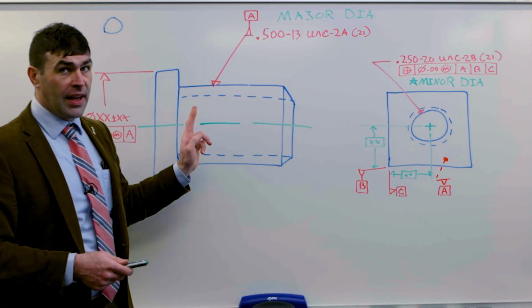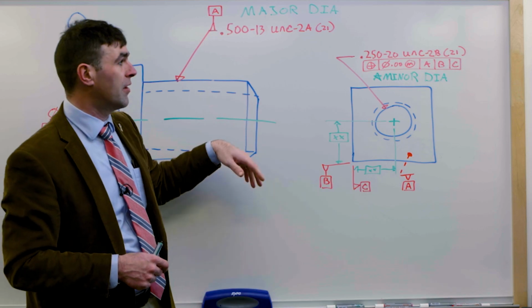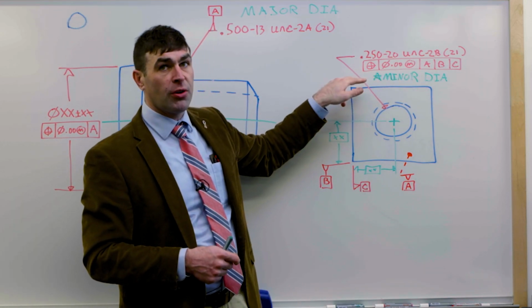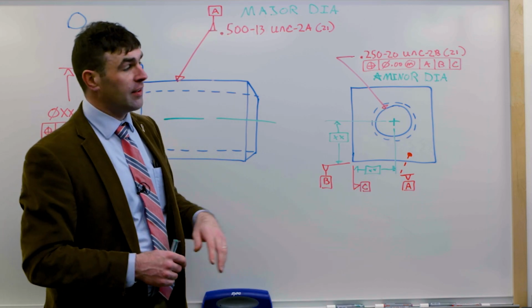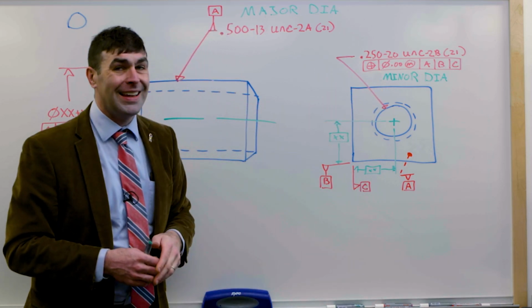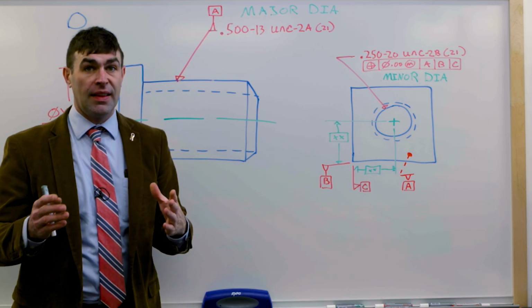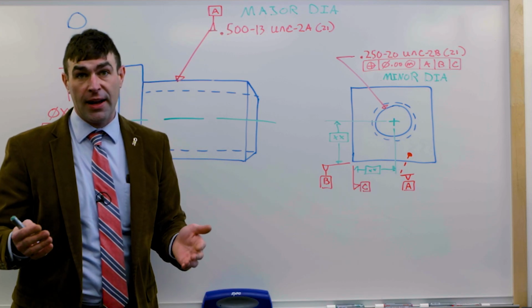And again, this is a datum reference. On the feature we're controlling, not a datum reference, we'll put it under the feature control frame. So, as I said a minute ago, beneath or adjacent. Here we're beneath, so we don't need a star. It indicates that we just need to find the axis of the minor diameter, the unrelated actual mating envelope